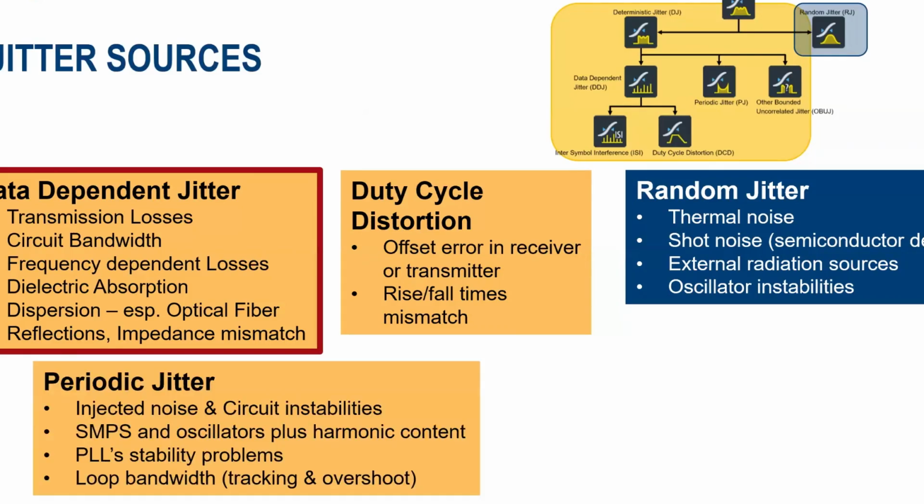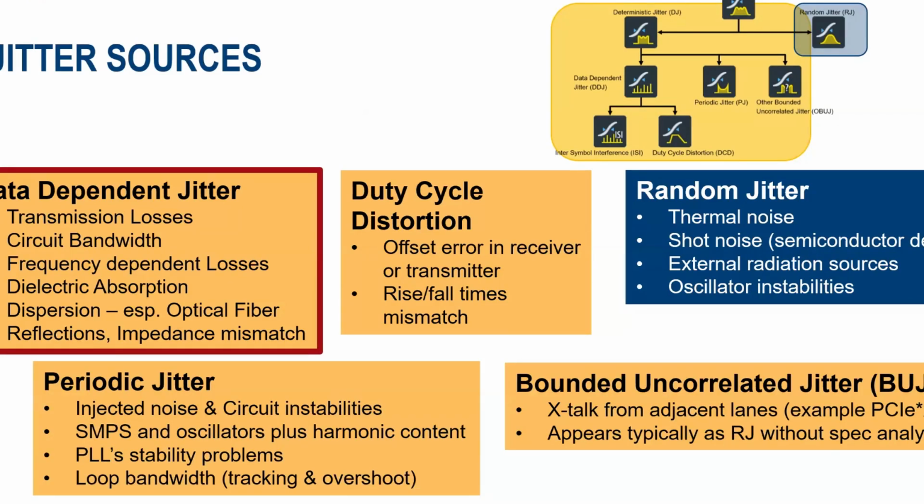So in the industry, measuring jitter, we've come up with a lot of different categories of jitter. And the reason this is done is because jitter sources have different, for lack of a better word, probability density functions. That is, as you observe a certain type of jitter over time, will it grow continuously or will it have some fixed range? And so the jitter pathologies or components that have a fixed range are referred to as deterministic, but rather bounded is maybe a better word to refer to them as.